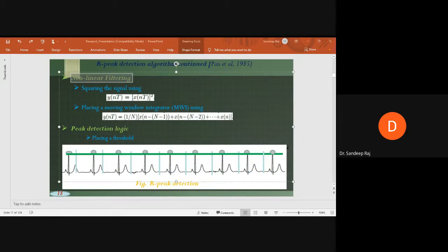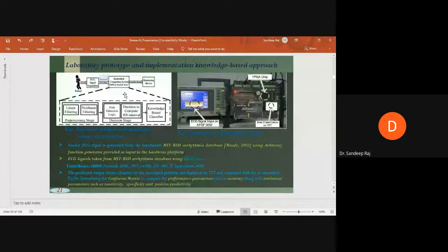In that, we have to develop the software and the interfacing. As you can see, we want an ADC. The ADC has been connected through SPI to this processor, and we require a DAC to see what input we have taken and what is being displayed as the output. We require both of these components, and we have designed this complete system. The algorithm, as I said previously, was developed in the C++ programming language in the Altium Designer environment. This is a board which contains the FPGA chip itself, and it gives us some of the IP cores of the processors.